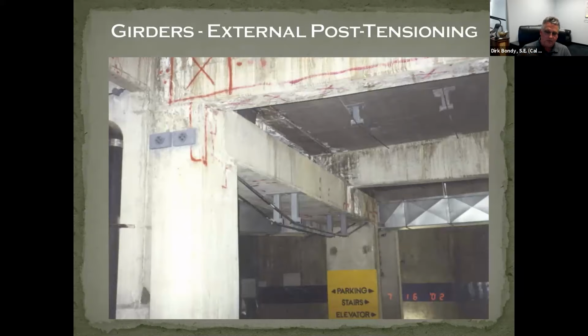So we're trying to keep it from loading the slab that's already had problems. But even during live load, they may touch each other. And so we have strengthened that slab from below, waterproofed it, done our best to keep that slab from further deteriorating, and then provided another slab on top. But that cumulative weight built up on these girders, and we had to do some pretty serious angled coring through these large columns to get that post-tensioning through. This has been standing there for about 16 or 17 years, so we're pretty sure it worked.